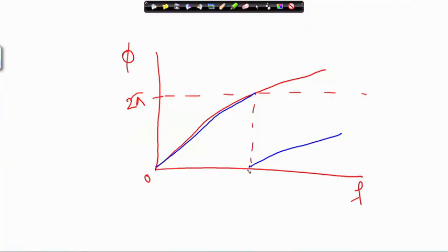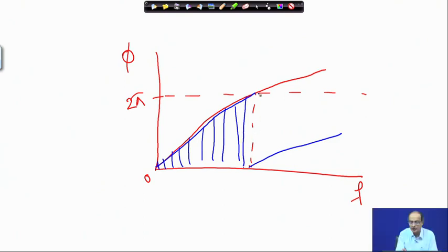The simple way this can be done is to follow, for each frequency, how much the change in the phase is. When the phase, due to this complex transform, has a jump, the value of the jump is about 2 pi. We know it is a huge jump. So, when such a big jump occurs, we simply add 2 pi and put it back in the real place.